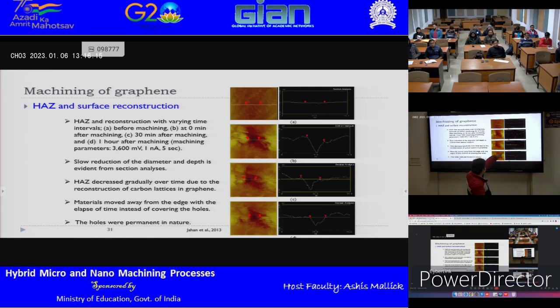There is some deposition of material, but as I mentioned, we were able to collect some other information. I think that color change is directly an effect of the temperature change also. Okay, and also some kind of phase transformation. So we are able to see some of those heat affected zones and recast layers.